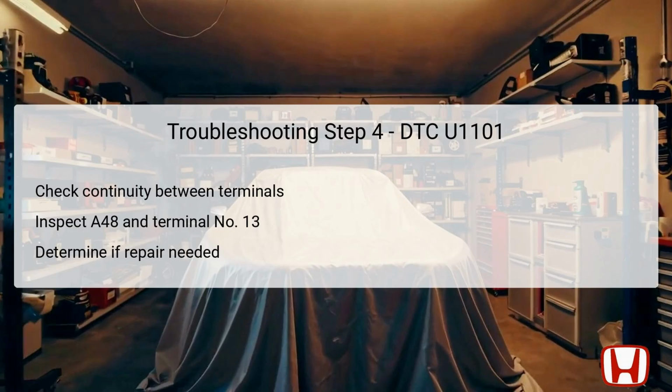This continuity test assesses whether proper electrical connections exist, indicating a functional link between key components in the communication system. If continuity is present, it suggests that there are no breaks in the wiring in that segment, and the troubleshooting can progress. However, if continuity is absent, it highlights an open circuit issue in the wiring that needs to be repaired. Identifying whether continuity exists is a critical step, as it allows technicians to delineate where in the electrical path a fault may lie. Depending on the results, the technician can ascertain the next course of action for repair or